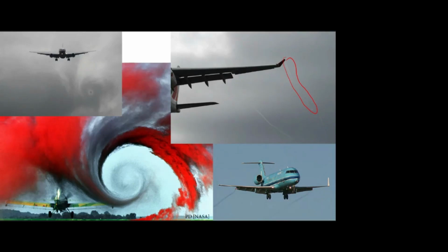Actually, here also we can see they extend the flap. Here also there will be a side leakage flow, right? Due to that, there is a wingtip vortex at the flap also. But see, this is a smaller aircraft. Mostly in smaller turboprop aircraft, there won't be winglets. So this forms a bigger wingtip vortex, and this will produce more induced drag.